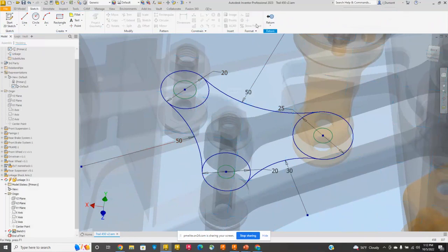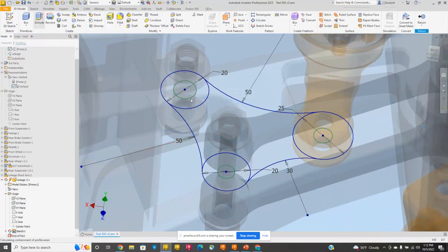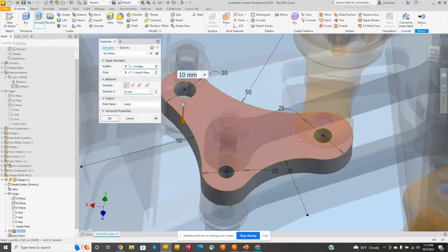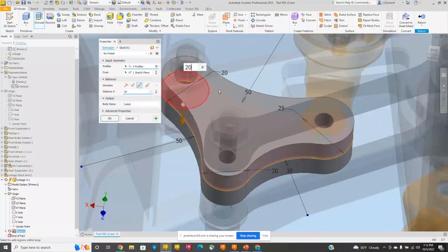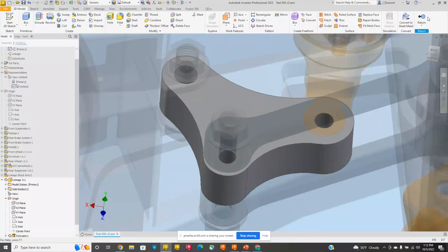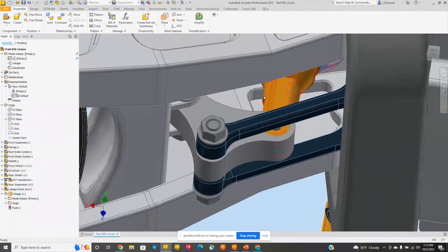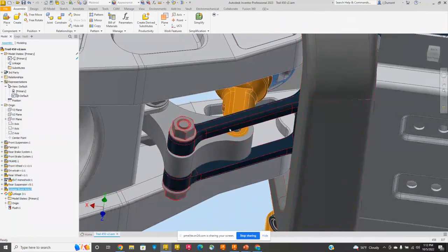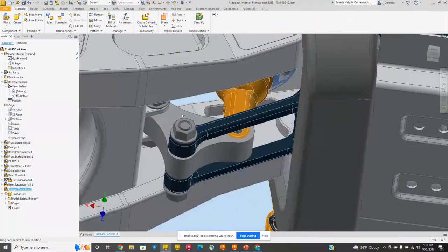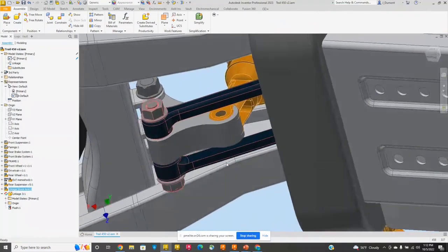So now what I want to do is actually make this a solid. So I'm going to extrude my geometry. I'm working in the middle of the assembly, in the middle of the part, so I want to extrude it in both directions. I've already measured it, so I need about 20 millimeters thickness, so I'm going to specify 20. So it's going to split it. It's going to go 10 in each direction, and this is good. That's what I'm looking for. The only thing that I've done here is just sketch some geometry, created my first particular shape, but just by doing that, the geometry is actually tied together and actually controls the animation of my assembly.